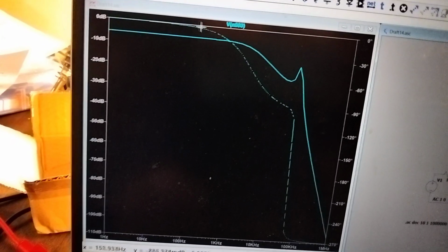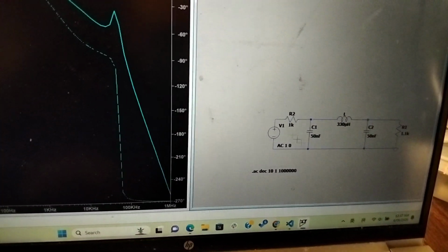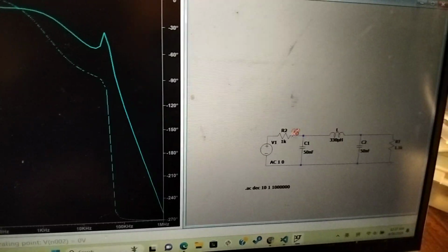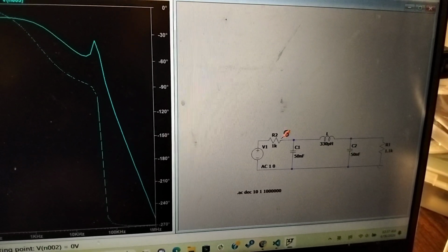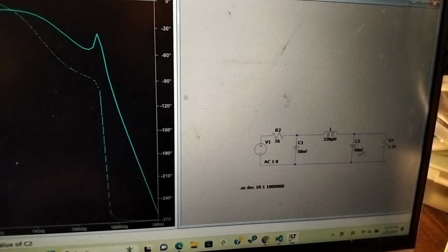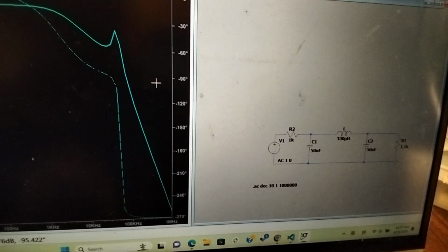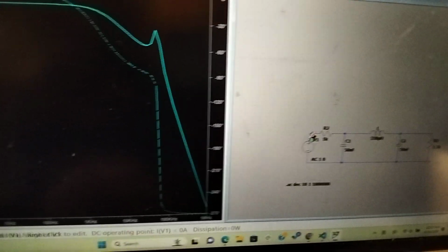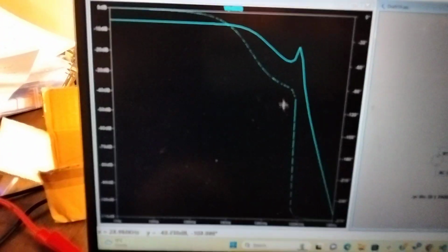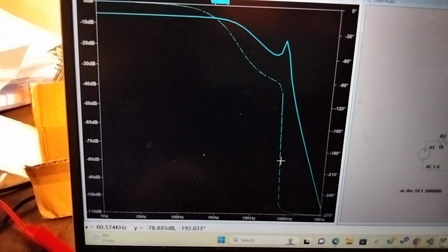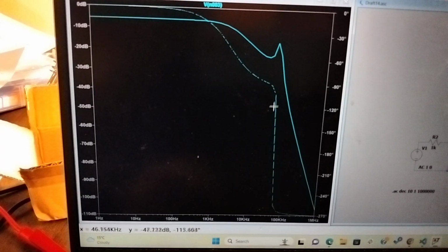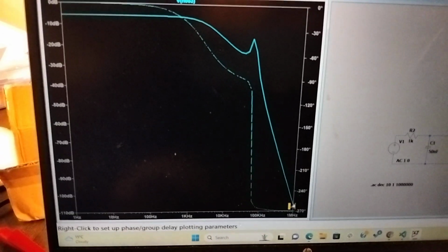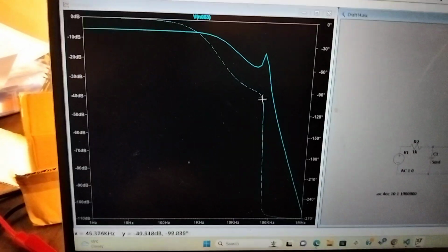Likewise, with the phase shift, it actually does not invert the phase 180 degrees always at the resonance. It depends on these two resistors actually. And in fact, if you remove this resistor, the phase shift will approach 180 degrees as the frequency approaches infinity. But by adding the series resistor, this 1K, the phase shift will basically be boosted 180 degrees approximately at the resonance frequency, not exactly though, and then it approaches minus 270. So it's actually a low pass filter.